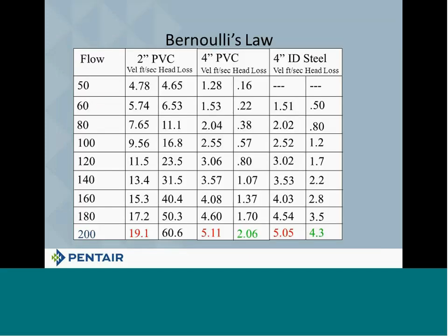So we'll put 2.06 in there. And again, part of the point that I'm trying to help you to realize is that even though the velocities are almost the same, the friction loss in plastic pipe is about half of the friction loss in steel pipe. Now, I'm not telling you to use plastic pipe. Please do not interpret it that way. That's not what I'm saying. What I'm saying is, whichever pipe you choose to use, make sure that you use the right friction loss for it, because it can affect how the pump is going to work.